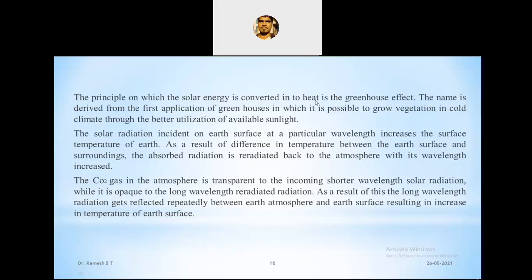This phenomenon has been recognized for some time in the construction of greenhouses, what I called a synthetic greenhouse, which can be quite warm on sunny days, even in the middle of winter. This has become known as the greenhouse effect. The solar collector used for heating is usually called a flat plate collector. A best example is the flat plate collector. Almost always it has one or more glass covers, although various plastics and other transparent materials are often used instead of glass.